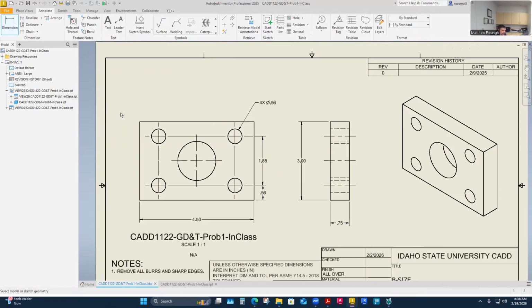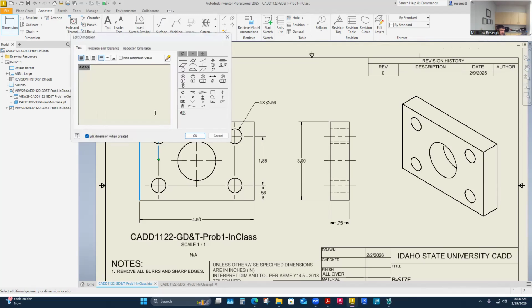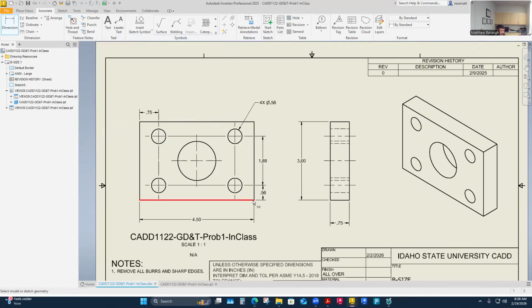So on our print, it pulled it from here. And the reason they're going to pull it from here is because I'm going to establish a datum to pull it from. So this is one that they snapped on there. You would think, oh, I'm going to pull from here to here, and you'd be right as long as you establish a datum to locate that.